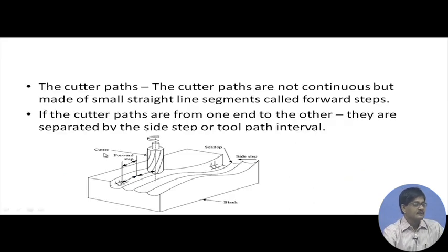Now, let us look at 3 axis machining in a little more detail. I have drawn some cutter paths. You can see that it is cutting out this material from a block. The freeform surface is gradually taking shape, but very prominently the cutter paths are existing. They can be seen on top of the surface, and they are creating minor deviations from the design surface.